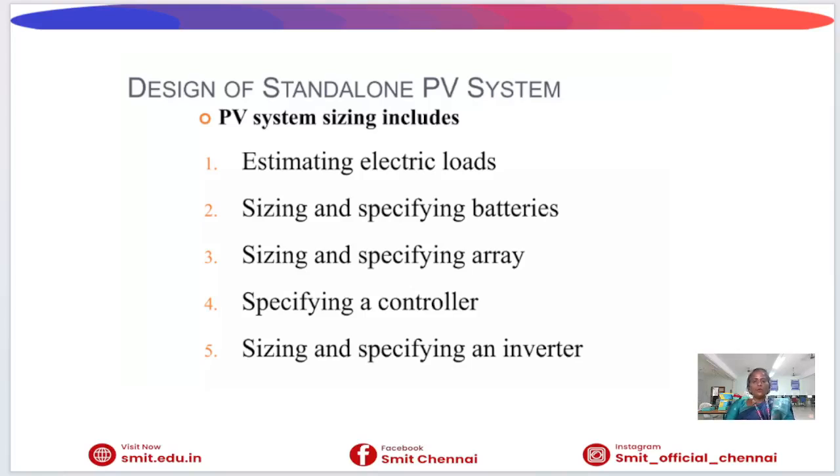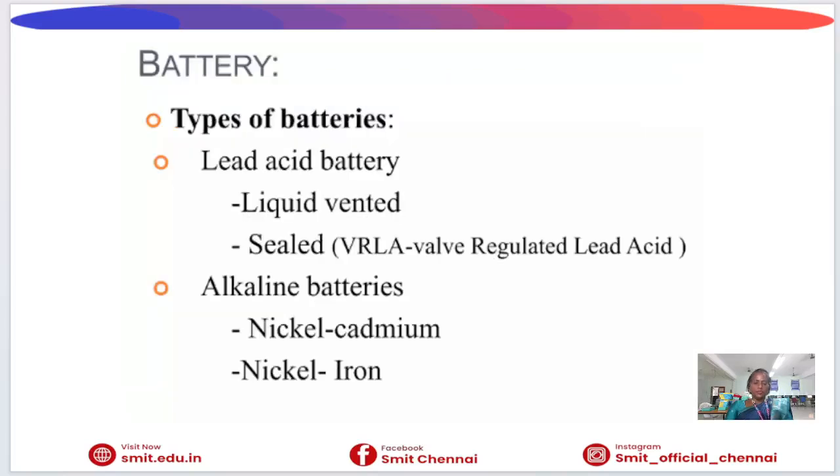Design of a standalone PV system. Estimating the PV system sizing includes estimating electrical loads, sizing and specifying batteries, sizing and specifying the array, specifying a controller, and sizing and specifying an inverter.